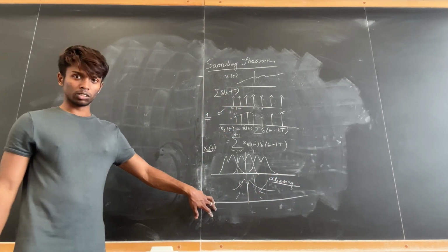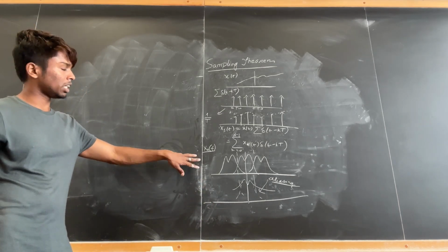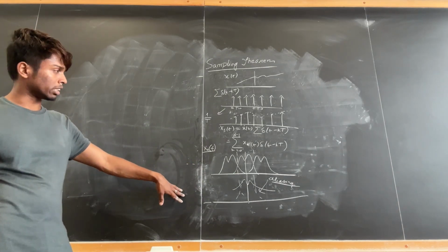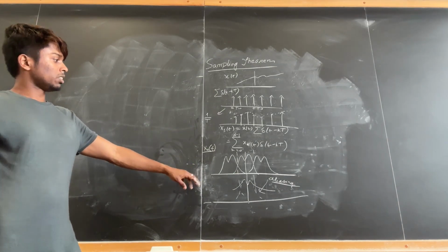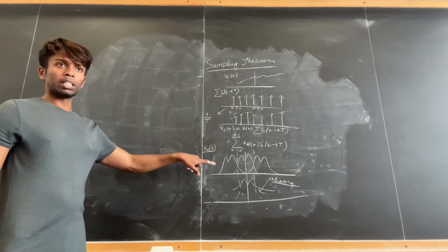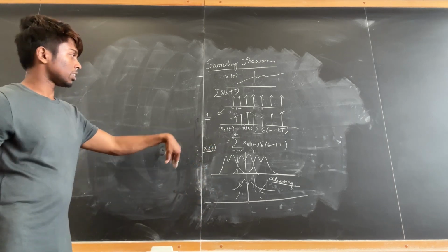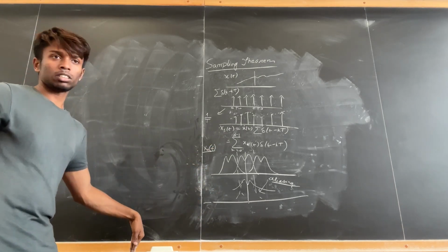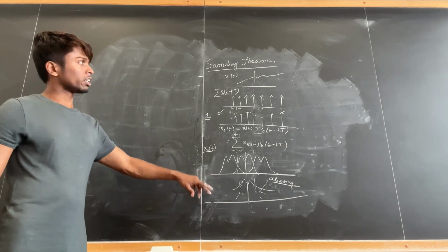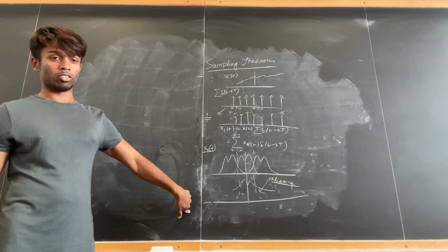This is aliasing. So we need low pass filters because of this reason. That's why we need LTI systems, we need to design filters and all those things. But use of the low pass filters in this scenario, where the sampling was not done at a correct frequency, resulted in this aliasing effect, and the signal which we retrieve back by doing an inverse Fourier transform after this is not really the signal which was initially in the beginning. So that is a wrong signal that we retrieve back.